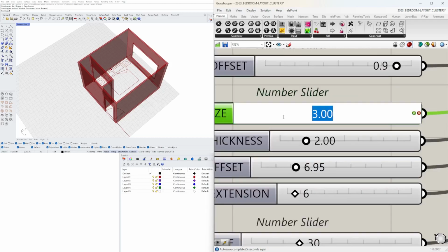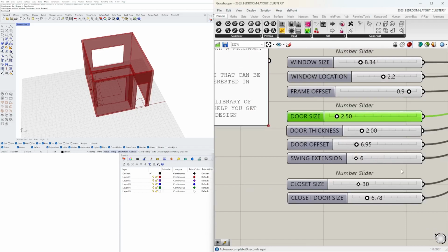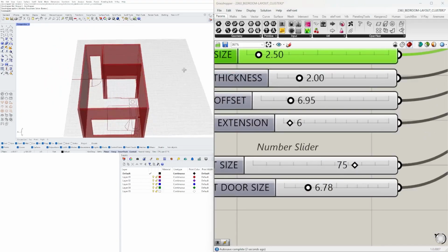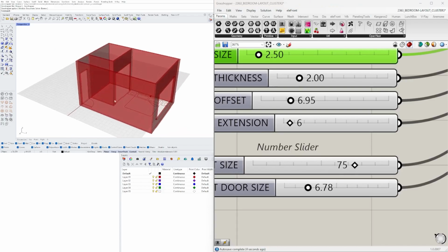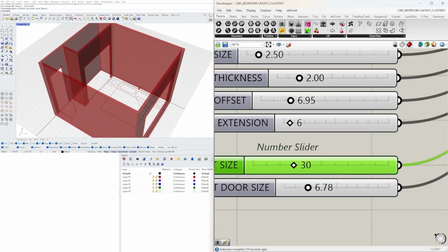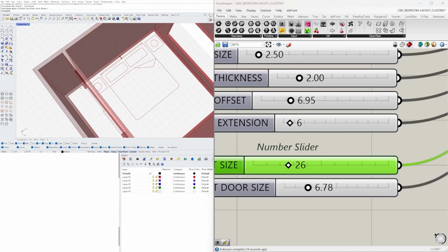3 feet, 2.5. Even if you want a large closet like that, say a walk-in closet, you can have this. Well, for this one, it's mostly, you don't want it to be any less than, minimum 26, 24 inches inside to inside.